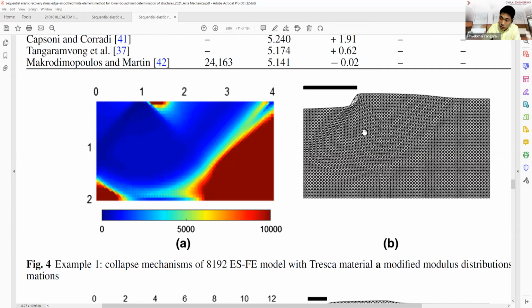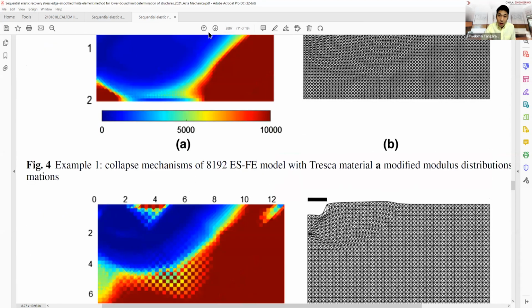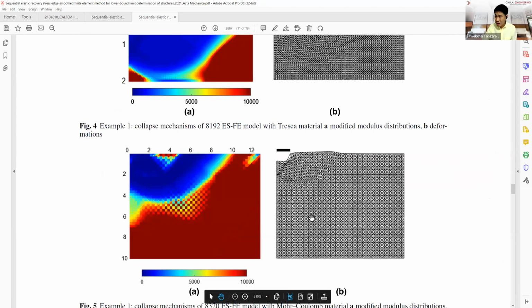If we push, it has a push-pull effect. We have the push here, and it transfers the stresses to the adjacent area, so that's why it hops up over there. The stress value has been shown. I clamp it, so I fix the boundary. You see that the boundary doesn't move at all. I define the boundary at the center, and it doesn't allow translation in the x-axis. The more we discretize the element, of course, the better the idea, and the stress starts to converge. But when we check the convergence, right?